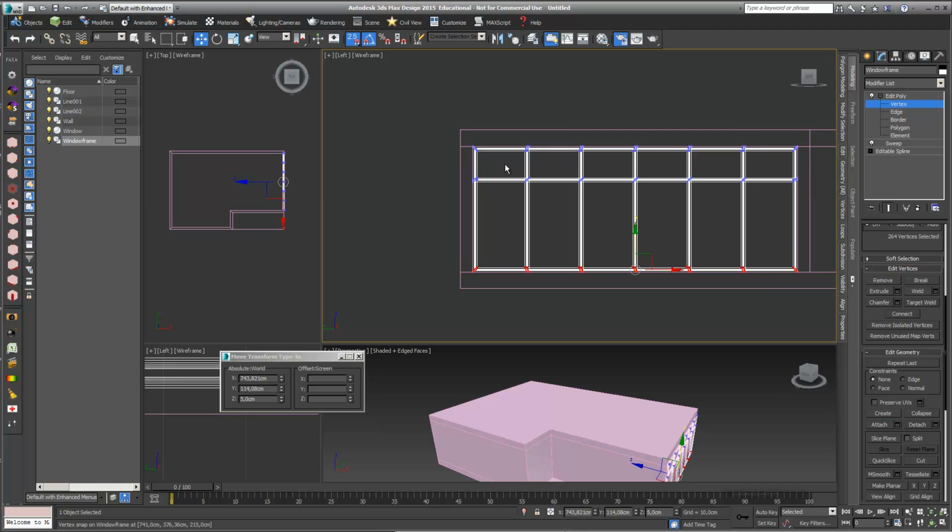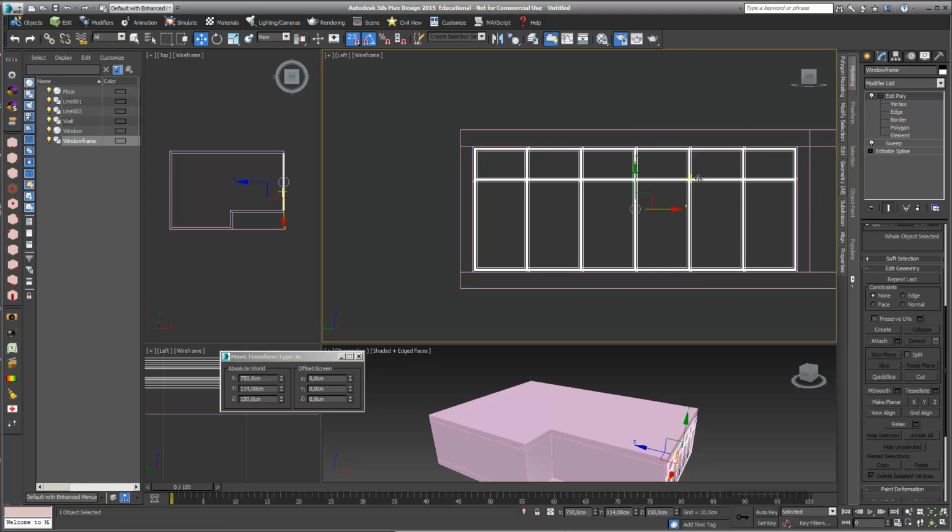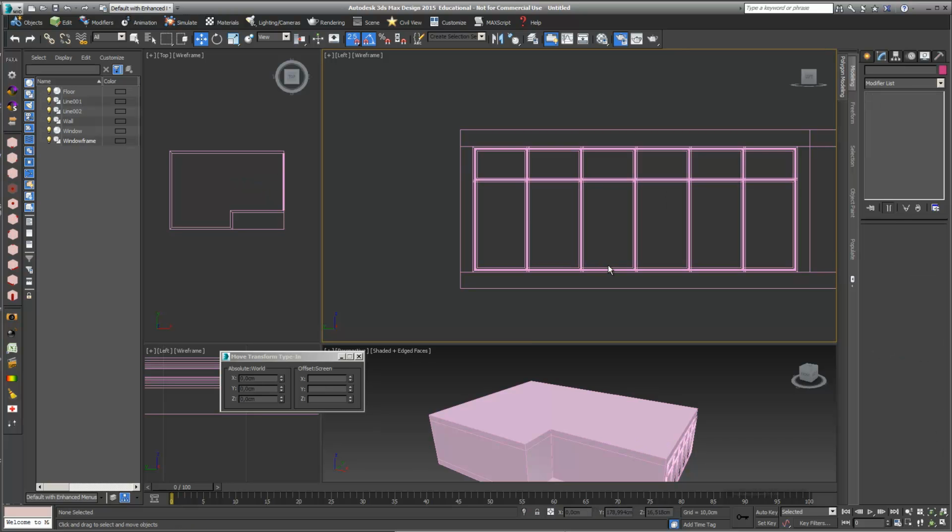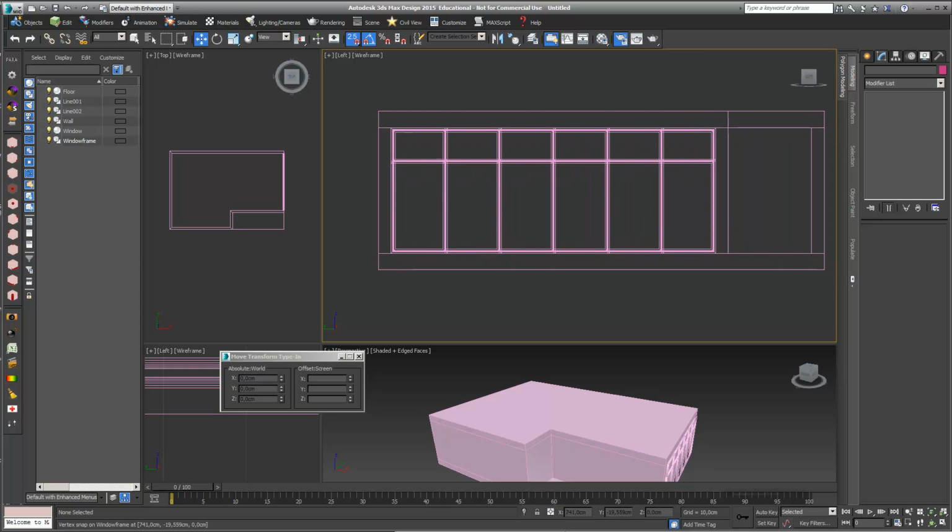If I know this already, it's better to adjust my plane underneath and already make it so that it fits at the end of the day when I extruded the window with my sweep modifier. The last thing you have to do is give your window frame a material, for example a metal material. You have to give your window material, best case Autodesk glazing, and your wall something like a wall paint material, and then you already have a really nice visualization.